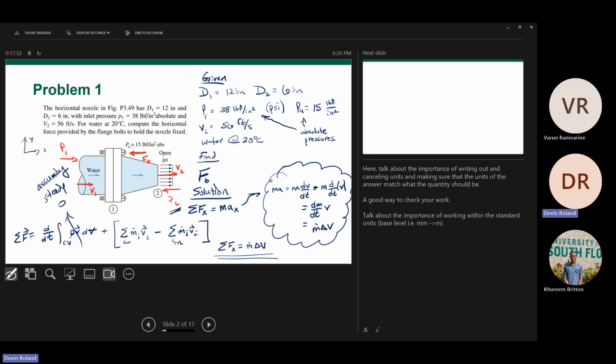Is it always like that, wherever the flow exits, P2 is going to be just the atmospheric pressure? Yeah. If you have flow that's entering the ambient environment, then the pressure there is equal to atmospheric pressure. The reason that P1 is not is because that's a cut of the pipe, and technically there's more pipe back over here. You're still in the system at that point.